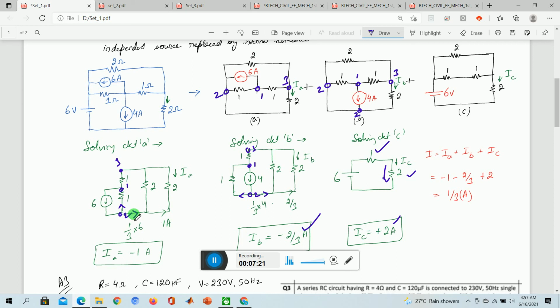The one which is going on the right will depend on its opposite resistance, that is 1. The net resistance to here is 1 plus 1 is 2. So 2 and 1 is 3. So the current in the right hand side is 1 by 3 into 6. And this current is split into again 2 parts, obviously equal. So this is 2 ampere divided by 2 is 1, and now the current which is moving up is 1 ampere, so obviously the down current is minus 1.